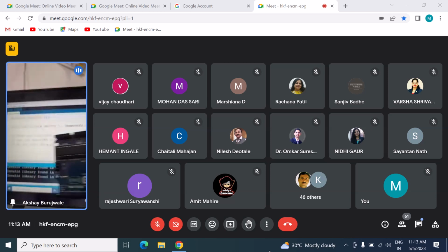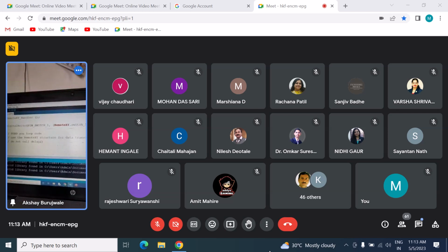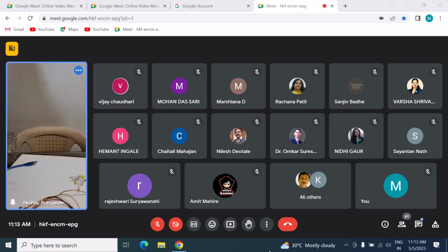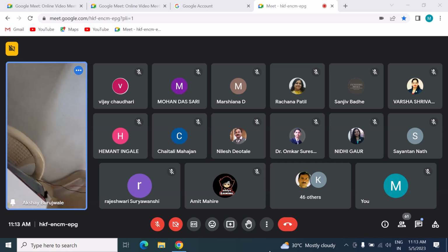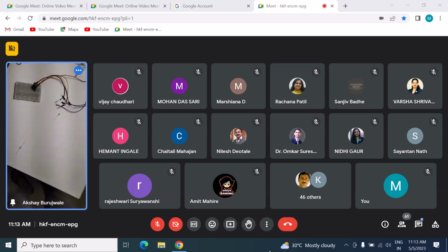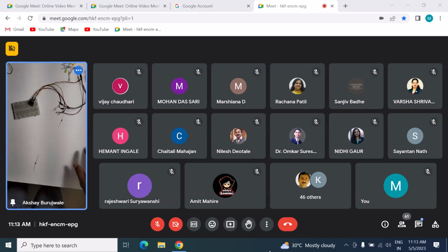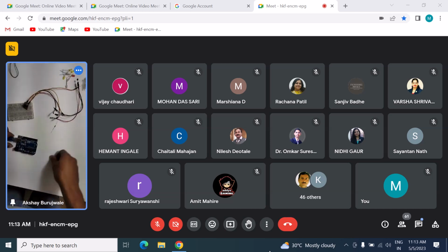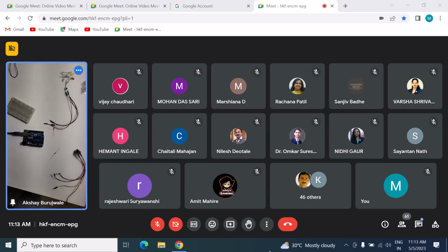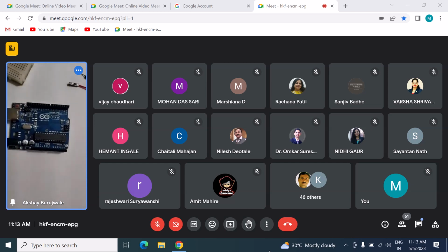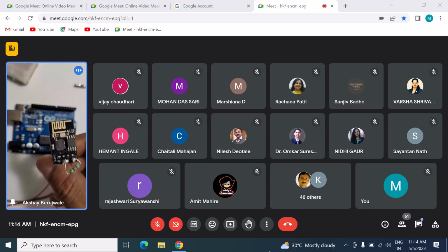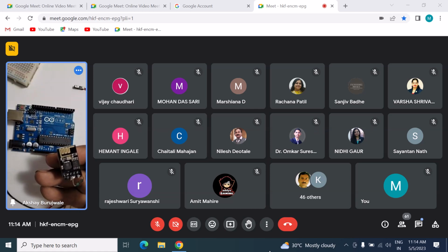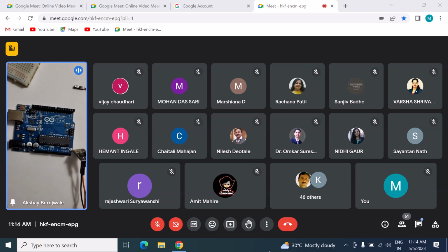Okay, so we are making connections with the board. One minute, I can manage some things. Okay. Here we have the Wi-Fi module. It has one resistor connected to the pin pull-up. These are 8 pins, where RX and TX, and this is VCC, and above is ground. Ground, and then you can go with the wires.